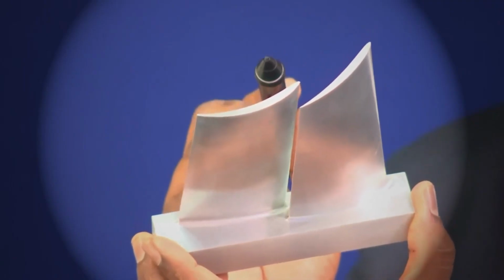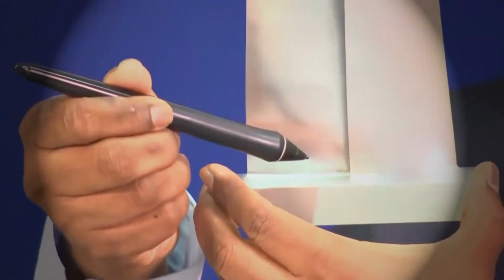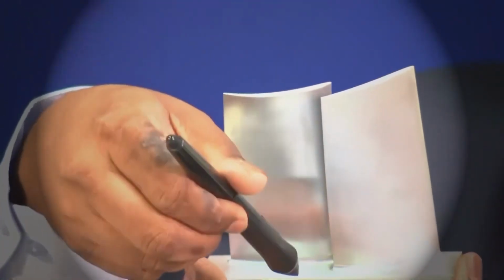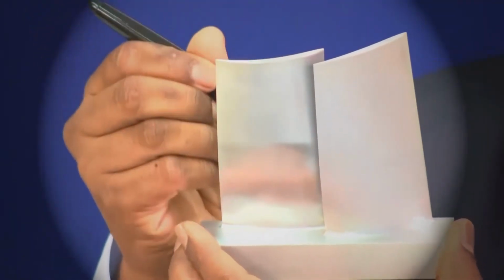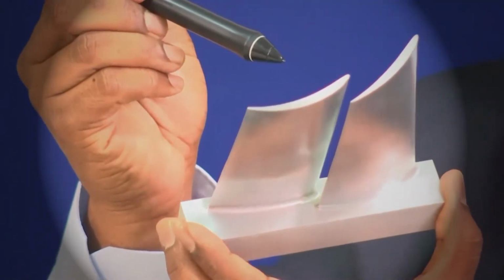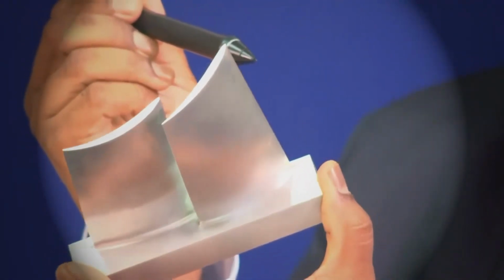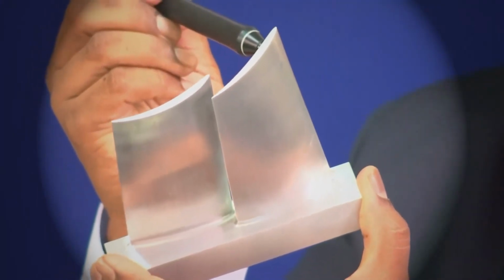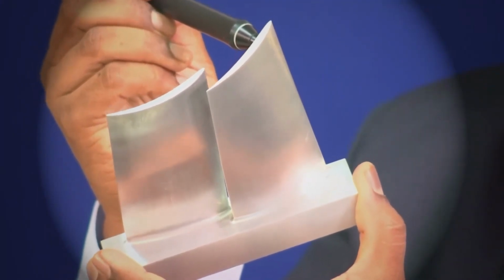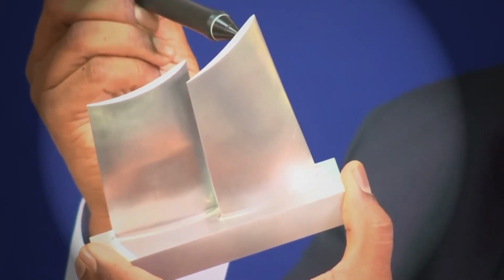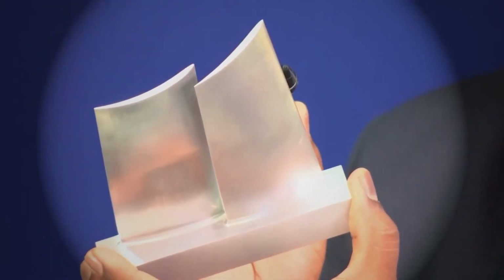But when we are working on the actual configuration, from hub to tip I will have different angles, and I need to manage my flow throughout my span, and in order to take care of that, we need to change our axial overlap. So this is a tandem bladed rotor. The experimental work is going on for this particular rotor along with the stator. In the next lecture, I will show you the stator that has been designed for this rotor.